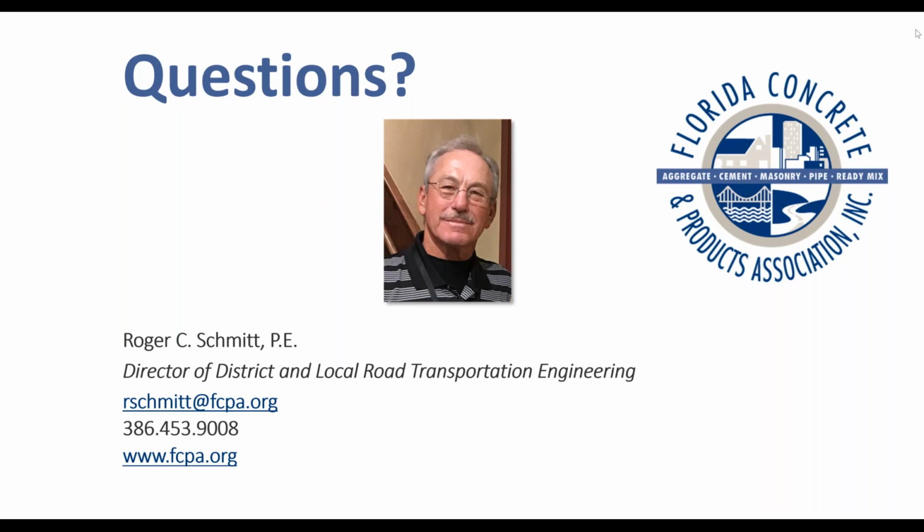I believe from my past experience that on 1792 going through downtown DeLand those were all tied curb and gutters to the concrete pavement. Some of the newer designs that I've seen, the DOT does not actually tie the curb and gutter to the concrete pavement.